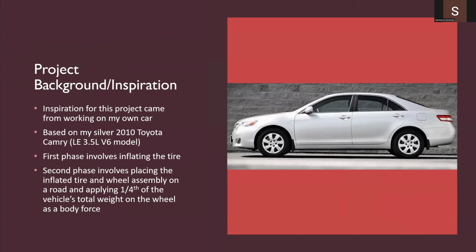It has size 16 tires, and the static analysis is broken into two phases. The first phase involves inflating the tire to 35 psi as recommended by the user's manual. And the second phase involves installing that tire onto a wheel and placing that assembly on the road, and then applying 1/4 of the vehicle's total weight on the wheel as a body force.